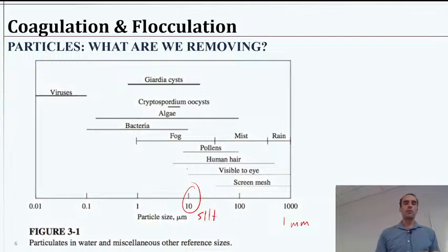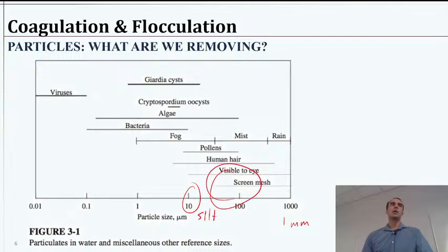Okay, so given all that, from the example we worked, it's a pretty reasonable example, we noticed we were not able to remove these particles. So with basic sedimentation, we're looking at removing particles that are probably more like in this range or higher. Now, that means when we do more advanced, aka we add some coagulation, we're trying to make larger particles that kind of shift anything that we can to the right to make them larger. So hopefully some of the bacteria even might stick to a larger particle and be removed even right there before we even go into disinfection.